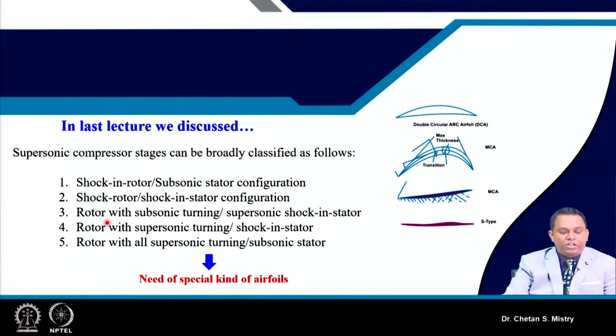Some other configurations: rotor with subsonic turning and supersonic shock in stator, rotor with supersonic turning and shock in stator, rotor with supersonic turning and subsonic stator. So all kinds of possibilities people have explored, and that has given a new vision for developing a very high per-stage pressure rise, and a whole new thought process for the design and development of the axial flow compressor.